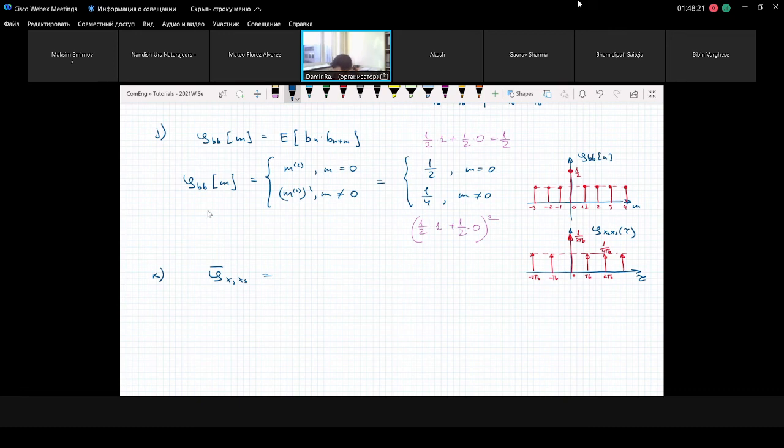Okay. And we can write analytically how it will look. In order to do this, I just need to split the delta pulse at 0 into two parts. And I can write that the autocorrelation function equals 1/4 TB delta 0 plus the summation, n goes from -infinity to infinity, of 1/4 TB times delta tau minus n TB.